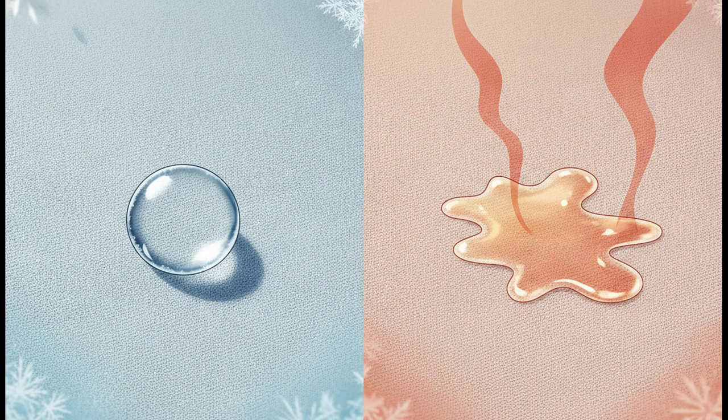It's also incredibly vital to remember that these properties vary wildly depending on the material and the environmental conditions. At room temperature, water's surface tension sits at about 0.072 newtons per meter. Mercury, on the other hand, is incredibly tight. It sits way up at 0.485 newtons per meter. Temperature plays a massive role here too. Heating water increases its molecular activity, which weakens the attractive forces between the molecules. This actively lowers the surface tension, which, by the way, is exactly why hot water is so much better at penetrating fabrics and getting your clothes clean.